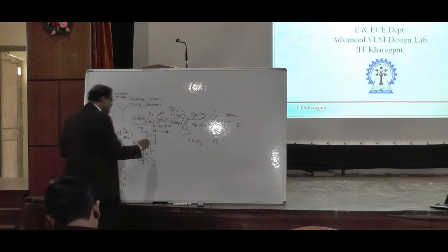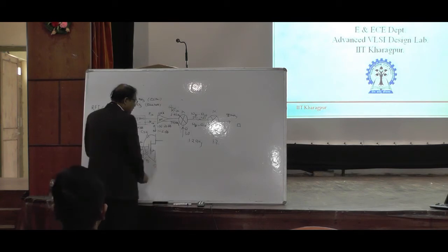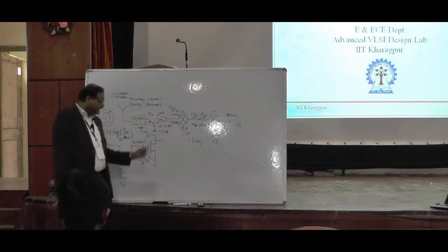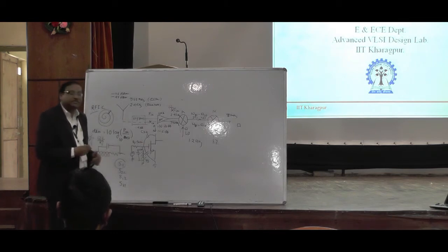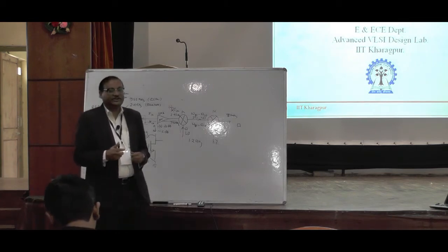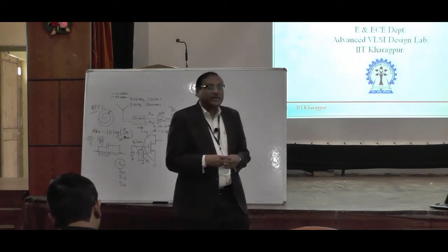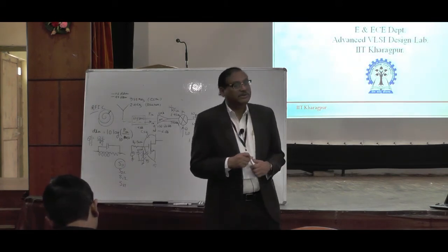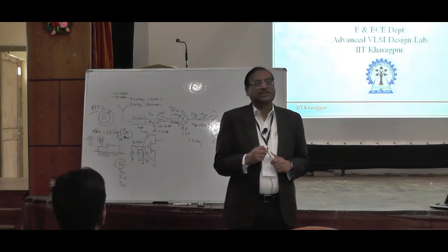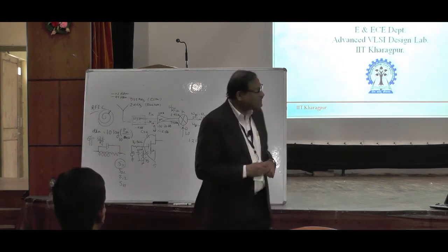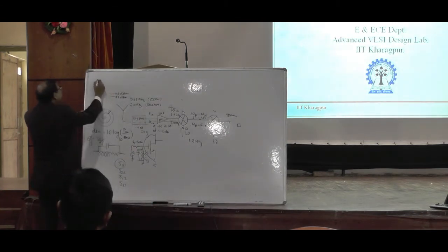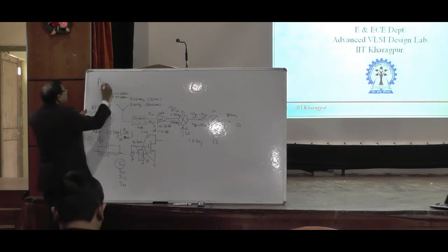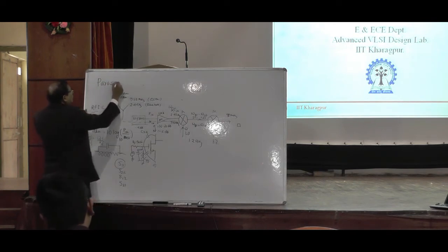The same thing also comes in the output. When you take the output, you are also having a load of 50 ohm. But again those capacitances will come and you have to negate them by a matching method. So that's the challenge of any front-end design, where the parasitic impedances are becoming the major challenge to overcome. If you look at the RFIC design in one sentence, it is nothing but a parasitic aware design. Parasitic aware.